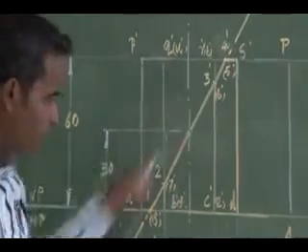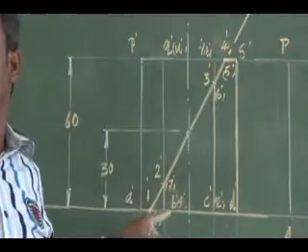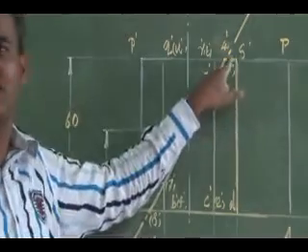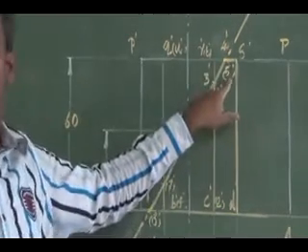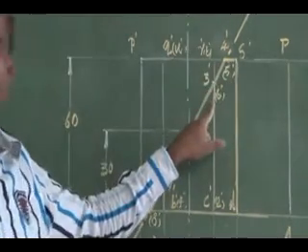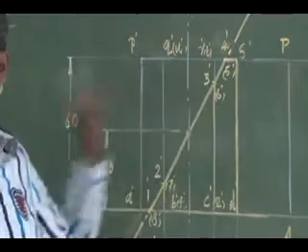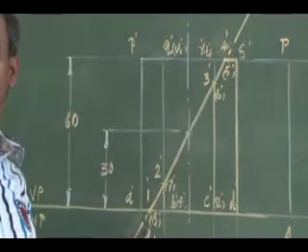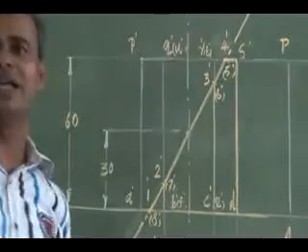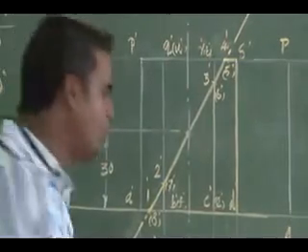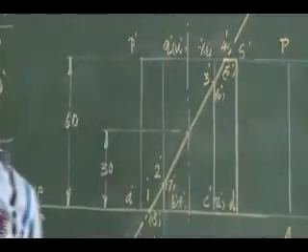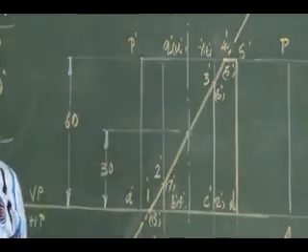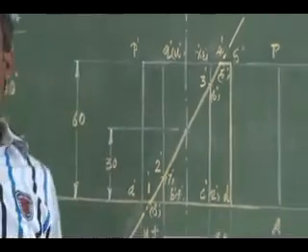Again I have to come back in the same manner along the cutting plane, looking for hidden cutting points. So there I will have a hidden base cutting point, then the top base cutting point, then hidden vertical edge points, again a hidden bottom base point. So totally I will have 8 cutting points. Listen here, how I have to transfer these cutting points to my development.